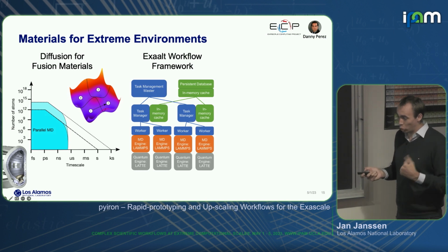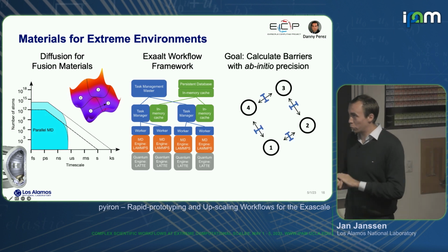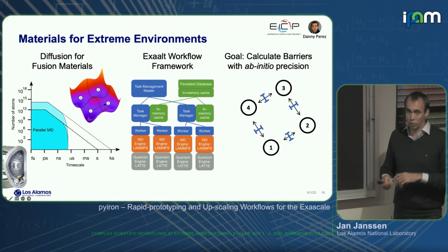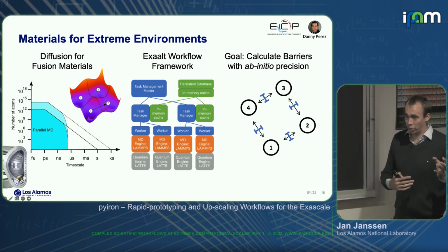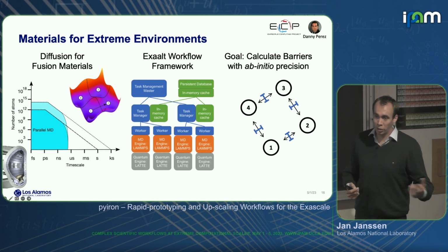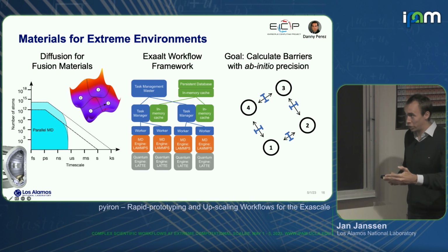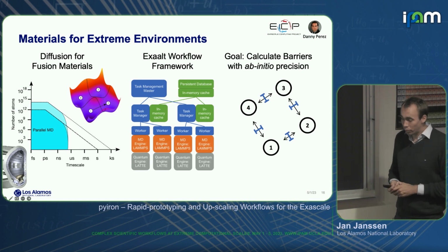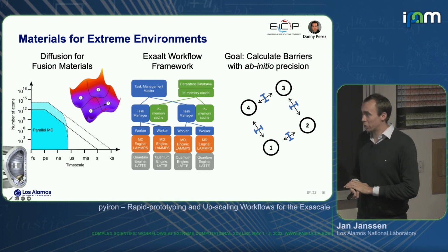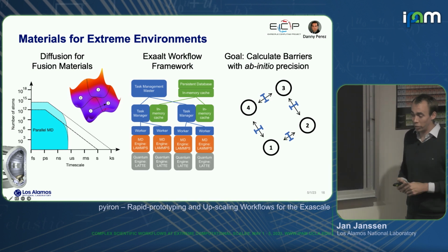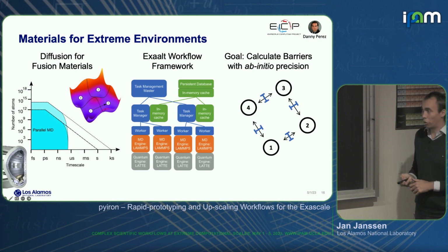And so the goal during my postdoc was to connect these two parts and calculate barriers with ab initio precision, right? So really trying to bring together the expertise from two different communities. On the one hand, the ab initio thermodynamics, and on the other hand, the materials for extreme environments, or primarily the diffusion properties using long timescale MD to really put barriers and hopefully even a quantitative understanding on the barriers.